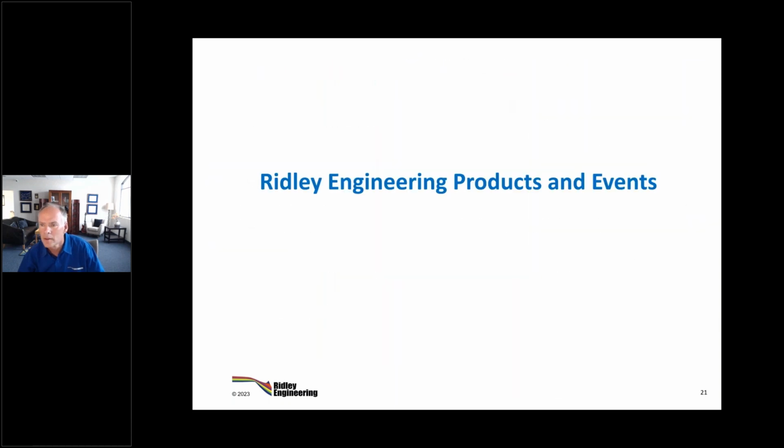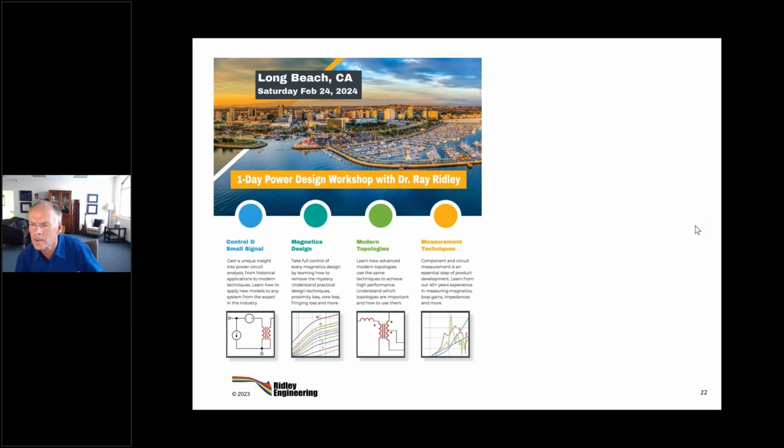Okay. All right, saturated inductor, layer. Slide 14, ladder model. For model fitting, what about phase shift introduced? Well, we run this ladder model in our simulations all the time. In fact, we've even done the small signal of the buck converter with core loss and with AC resistance loss.